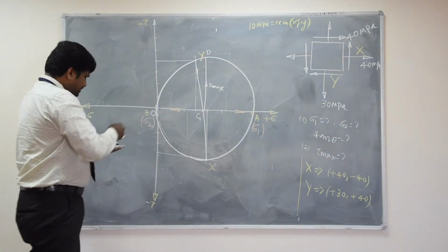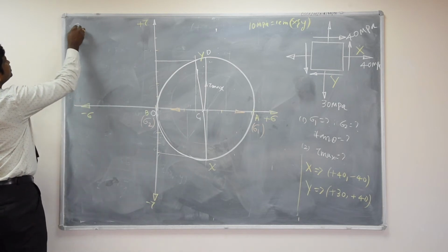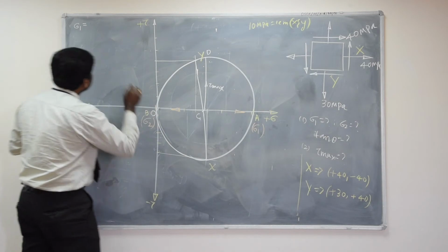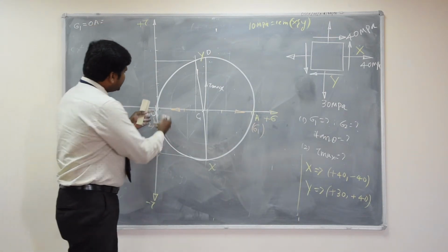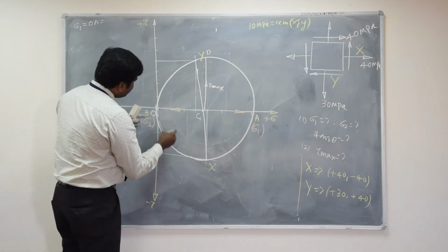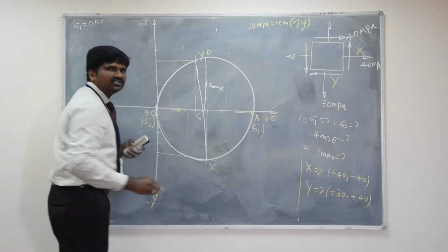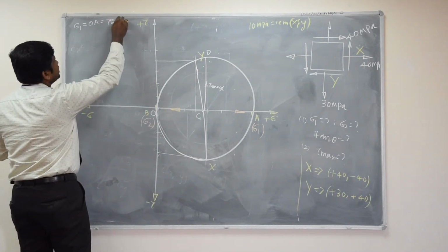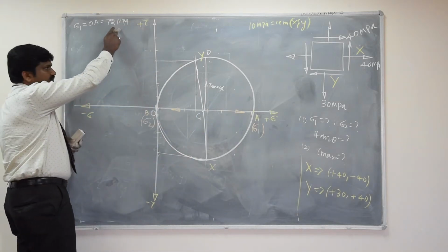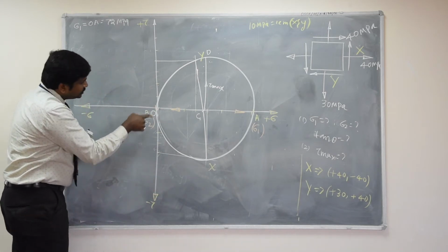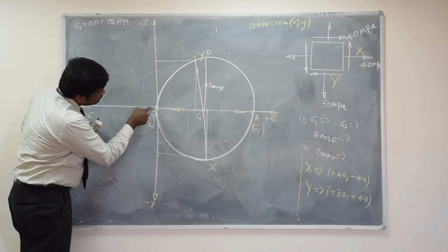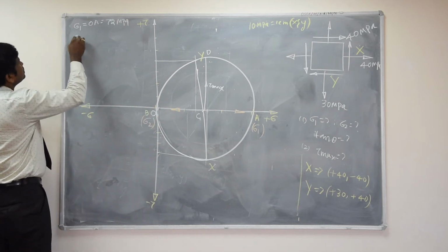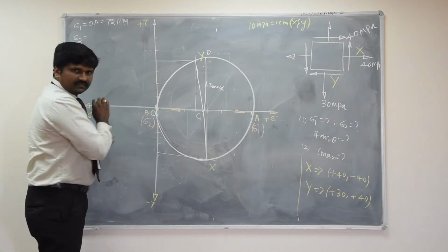Okay. Now to measure the distances, you can straight away measure directly. Say sigma 1 is equal to, what is sigma 1? It is the maximum principal stress. It is from O to A. So you take any linear scale and just measure it directly. There is no need of any conventional thing. So if it is, for example, 10, 20, 30, 40, 50, 60, 70, around 72 MPa. This is not an exact solution, it is an approximate solution. If you do it on a graph sheet, you will get exact solutions. So approximately with respect to this diagram, it is around 72 MPa. Then what is the minimum principal stress? The minimum principal stress is here. In this diagram, this intersection is taking place on the negative axis. So this would be approximately -2 or -3 MPa. So sigma 2 will be the distance O to B. It is O to B.